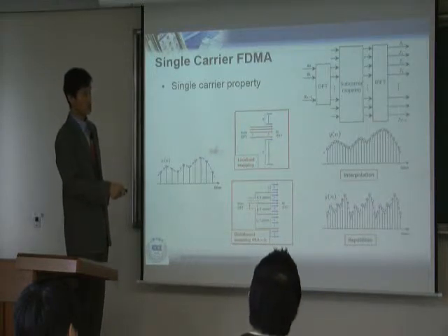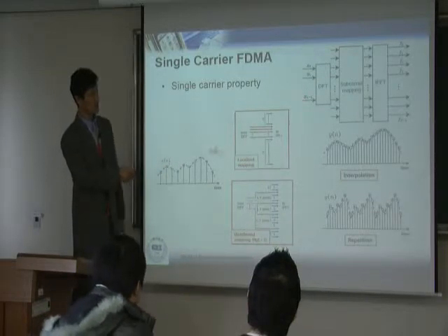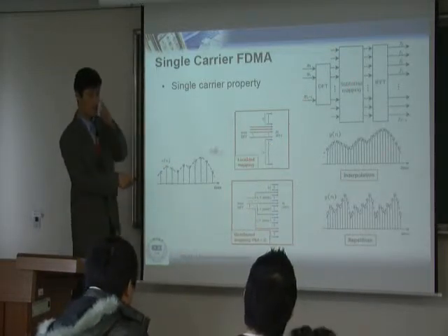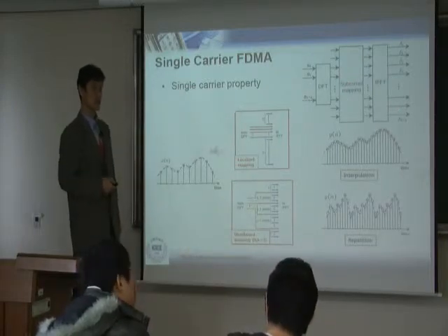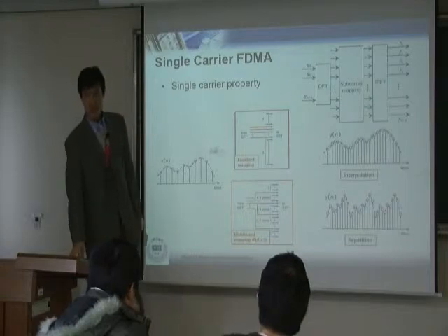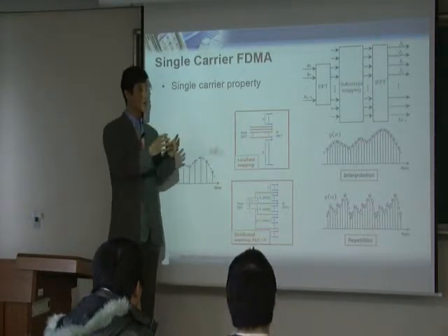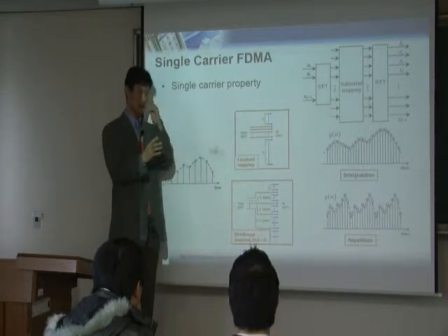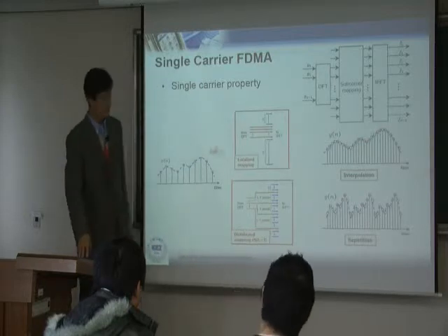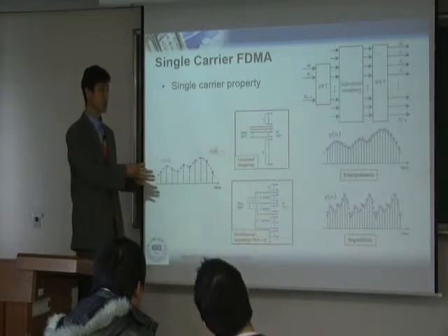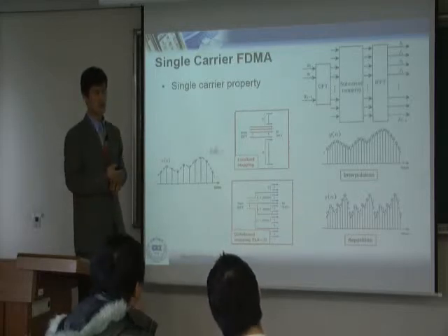So this is the output. This is the input here. And for this subcarrier mapping, let's say you do it this way. You simply do the zero padding, then the output will be interpolation. In signal processing, the same thing happens, right? Let's say you have frequency domain samples, and then you do a zero padding in frequency domain. Come back to time domain, and you have interpolation. So one domain is zero padding, the other domain is interpolation, in signal processing.